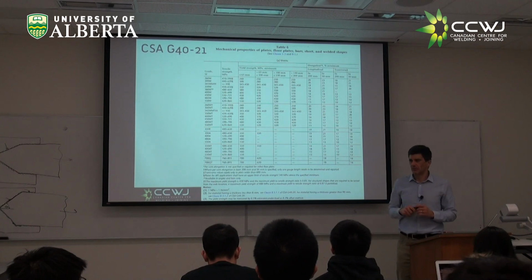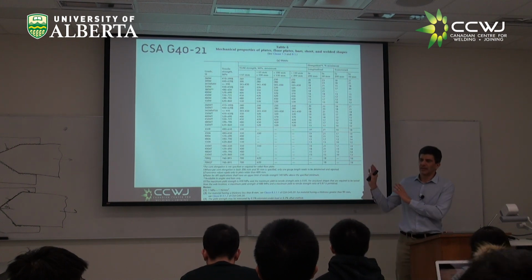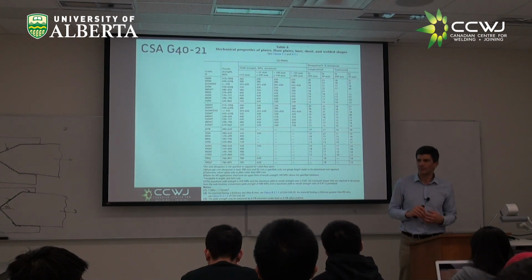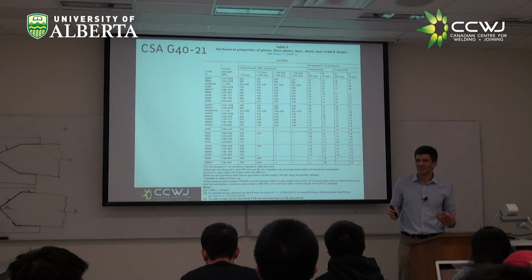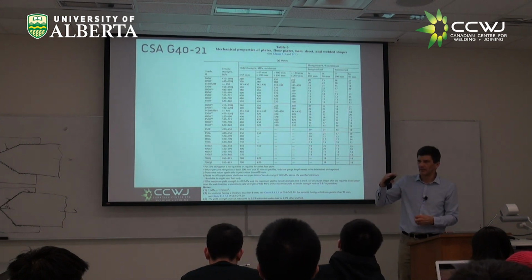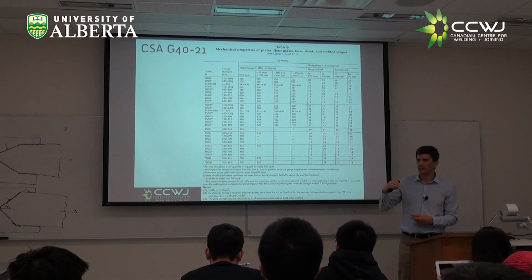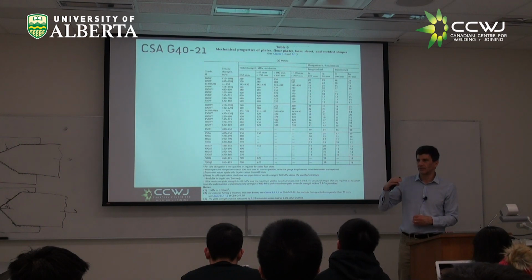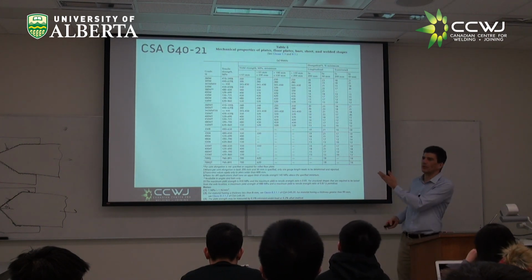and you're fine. So you're going to see in previous exams, I asked, okay, I qualify my weld and I design my fillet. If I have lower heat input now, my weld is going to be stronger. Should I redo my calculations? The answer is no. You do the calculations according to all the standardized procedure, these standardized steps, in which you don't get credit or you don't get knocked down for the different strength that comes with different procedures. Right? That's the same with configuration you have here.